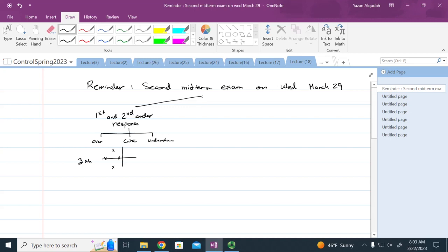The second topic is going to be the stability and using Routh-Hurwitz to determine stability. What happens if the first column is 0? If we have a row of 0, and how to populate the table and be able to tell the number of poles in the right half plane.